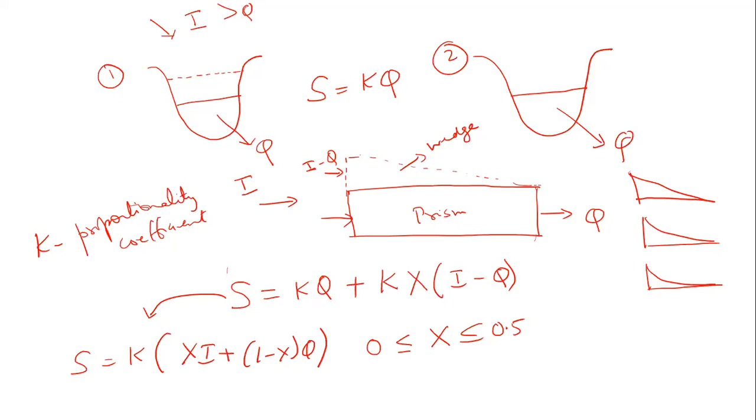So if I increase the flow rate, the water level will increase a little bit, but it will still remain within the channel. I have to keep increasing the flow rate for the channel to overflow and then begin to inundate or flood the surrounding areas. But as long as the flow rate is below a certain value, whatever flow rate is being passed through the channel has the ability to be accommodated within its own cross section.